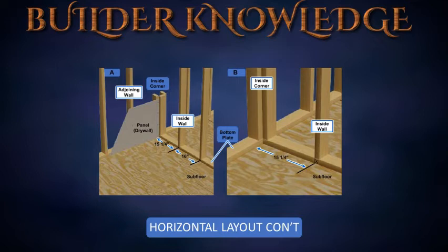Rough door and window openings. Mark on the wall plates the dimensions for the widths of rough door and window openings. Rough openings are calculated based on door or window width, finish frame thickness, and a 1/2-inch shim clearance at the sides of the frame. Door and window schedules on prints may provide rough opening dimensions. You must calculate the rough openings if the schedules do not include them.